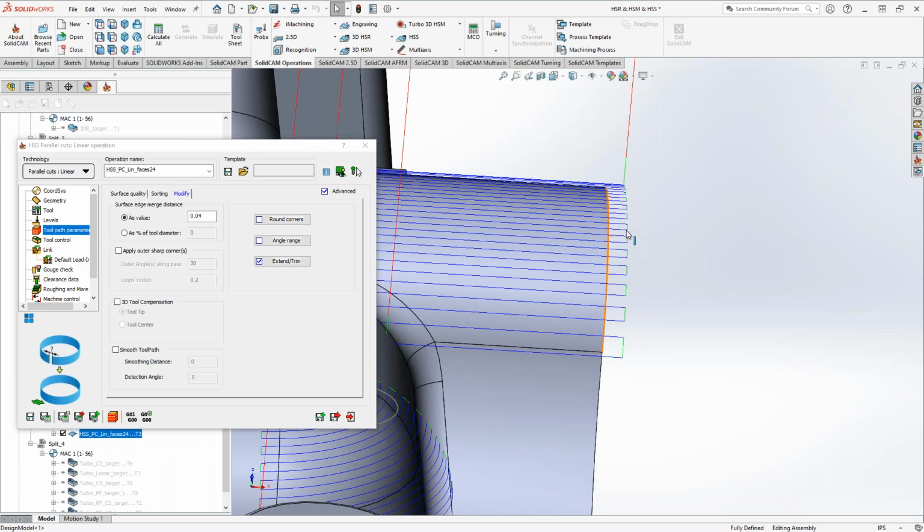There have been some 5-axis parts that I've had to help customers with where it's a translated file from some other design or some other software, and if you've ever done 5-axis, you know that the geometry really drives what happens in 5-axis. And if that surface is good to a certain point, and then after a while the geometry just goes crazy with curvature and you can't really get a clean 5-axis toolpath, sometimes you can actually just take the clean surfaces and extend them, and then you get that toolpath leading off the part.